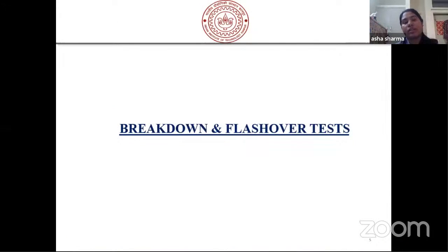So breakdown and flashover test. Before discussing the breakdown, let's say we are having two types of insulating system: one is the self-restoring insulation and another is the non-self-restoring insulation. For the breakdown, Dr. Alok has already discussed the solid, liquid and gases breakdown, so let me get into more about it. If we are having air as an insulation, then if the breakdown occurs, it is called the self-restoring type of insulation. Means the breakdown of the air will occur, but again it will attain its dielectric strength.